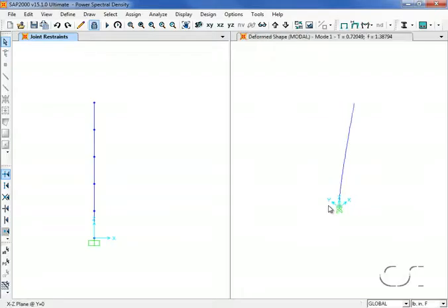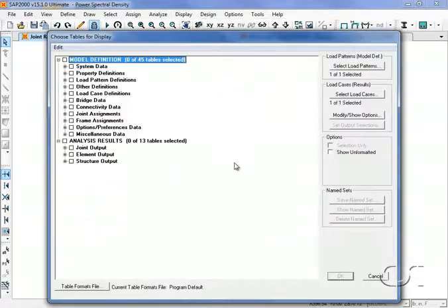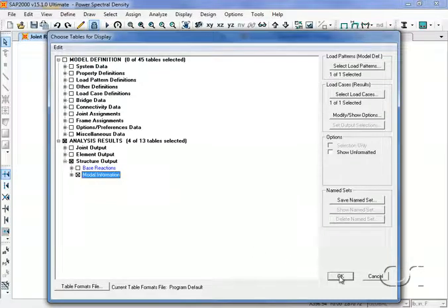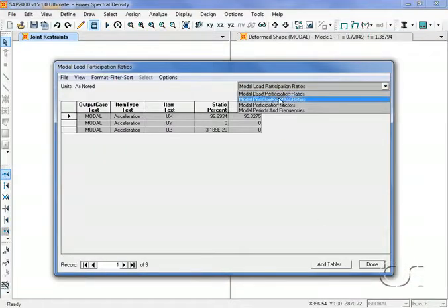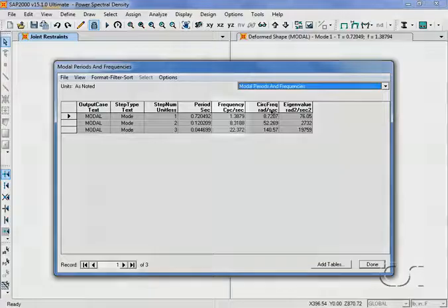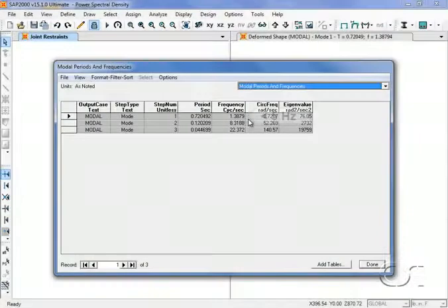spectral density curves. With the analysis complete, we need to determine what frequencies fall under our 5 Hz cutoff on the random forcing function. Our period and frequency table shows us that just 1 out of the 3 modes at 1.388 Hz occurs below 5 Hz.